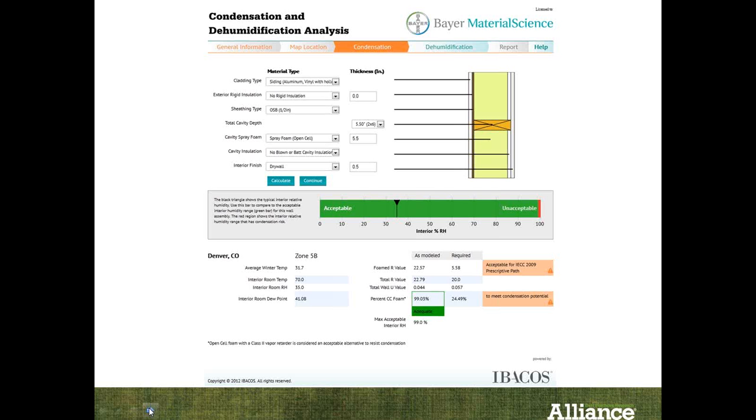Sure, and then back to the perm. So at 5.5 inches, you have a perm of 3.8, not quite a Class 2 vapor retarder. So as Anthony said, you would consider putting a vapor retarder coating either directly over the insulation before drywall, or you could apply a vapor retarder coating over the drywall to prevent any vapor diffusion. And as we already have identified that primarily we need to focus on air and then vapor as well, definitely not something to disregard. But when we have large delta Ts between the indoor and outdoor temperatures, and we have relative humidities that can create a vapor diffusion scenario, absolutely need to consider putting a vapor retarder coating on the drywall or the foam itself.